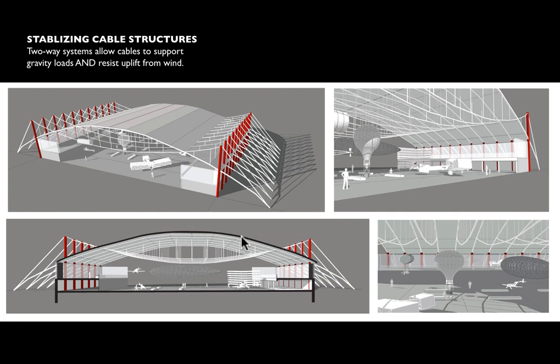And we can imagine that the roof load under normal circumstances is here going to get carried by the negative curvature cables. This cable is going to go into tension. It has compression struts here that are going to transfer the load of the roof down to that cable. The cable is raised up by these compression masts on either side.